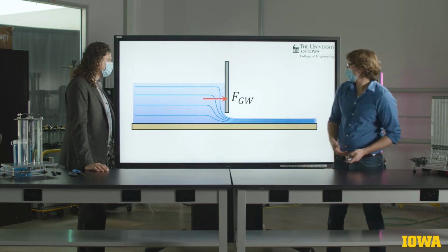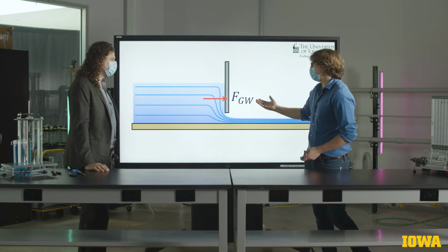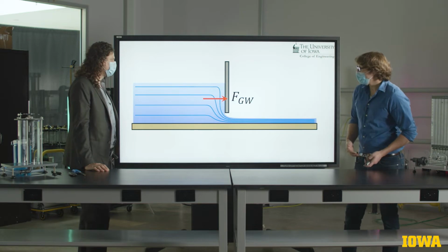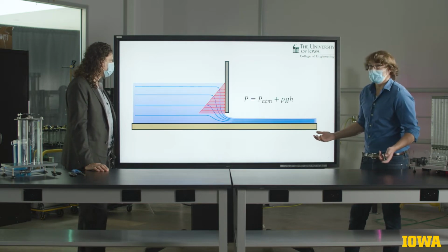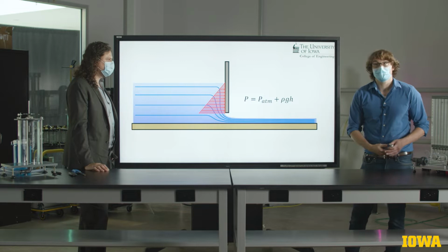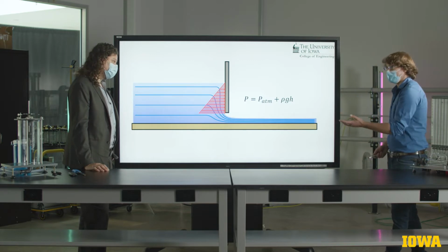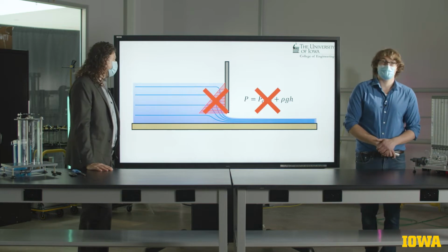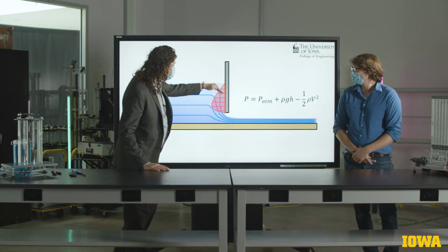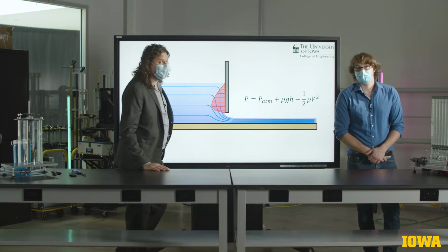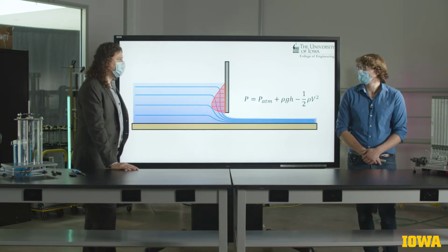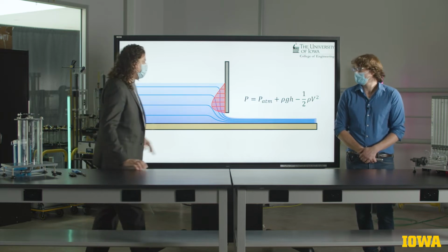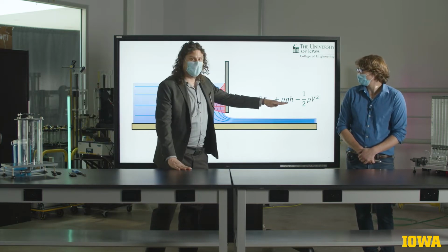And as Ricardo mentioned, to find the force exerted on the gate by the water, we might be tempted to use hydrostatics. In fact, many people will try this for the first time. But is this correct? That would be wrong. The reason being that the fluid is moving at the interface of the gate, and that's going to create a differential type of pressure that we know from our well-studied by now Bernoulli equation.